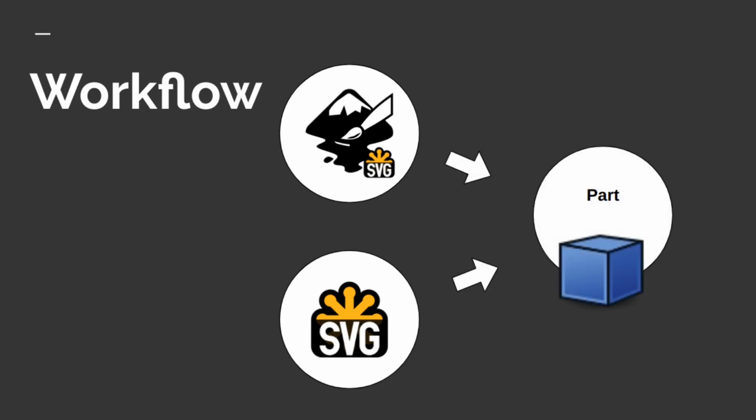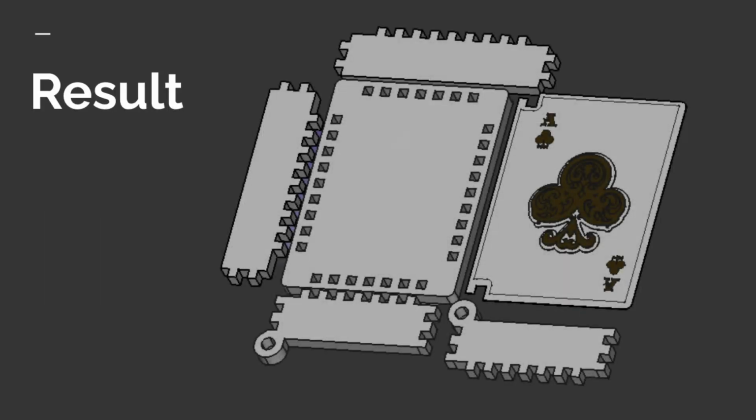So this is a bit different from part design. The part workbench uses Boolean functions and is basically the Swiss Army knife of FreeCAD. Our end result is taking an SVG from a laser cut project, using Extrude and Boolean operations to turn that 2D object into a 3D one that we can later use in CNC or 3D printer, rather than going down the laser cut or card cut route.